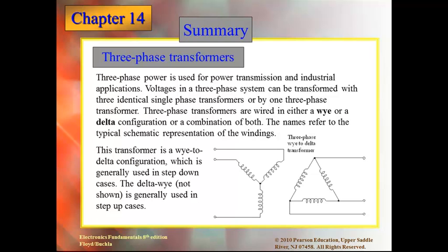Then the last thing to talk about is three-phase transformers. Three-phase power we've talked about before. Comes delta or Y. In the delta setup, we have straight voltage. In the Y setups, we have voltages determined by the square root of 3. So 120, 208 is a three-phase Y voltage, 480, 277, whereas 240 three-phase or 480 three-phase are straight delta setups. Again, it's still power, so it can be transformed. We just need 3 windings to do it.